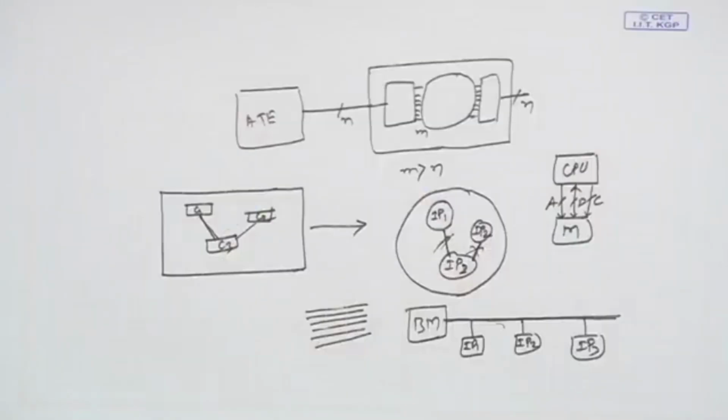You cannot go on hanging devices from the bus. That will increase the capacitance of the bus, and it will also increase the resistance of the bus. So, the delay of the bus will become unacceptable after we have connected a few devices to the system. On the other hand, we want the maximum parallel communication.